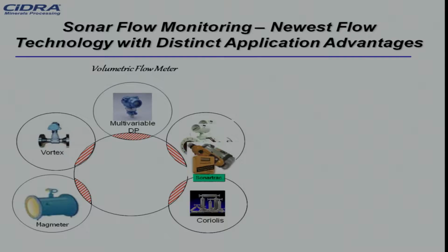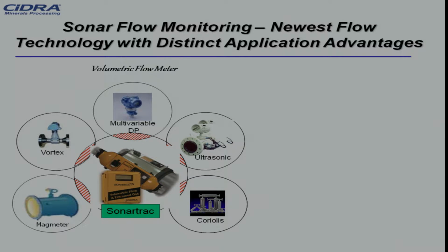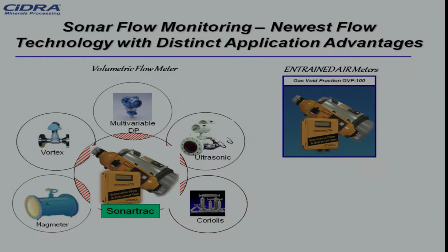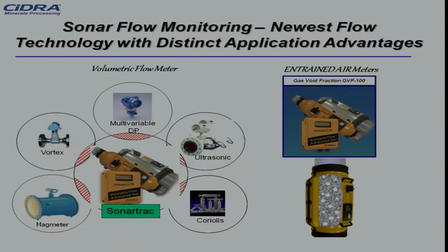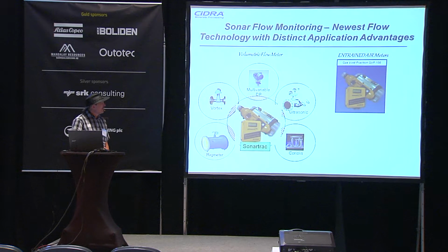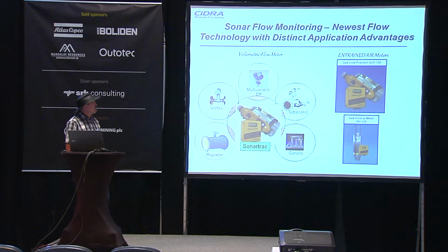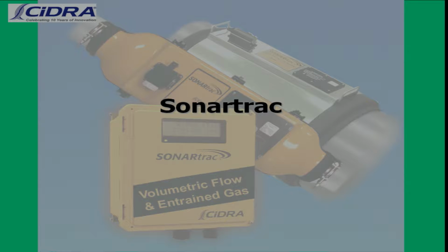So we are talking about the newest flow measurement technology, Sonar. That is the only technology that also simultaneously can measure the volume occupied by air bubbles within the pipe and correct the errors the bubbles are causing for density measurement. We do have also gas hold-up measurement for flotation optimization.